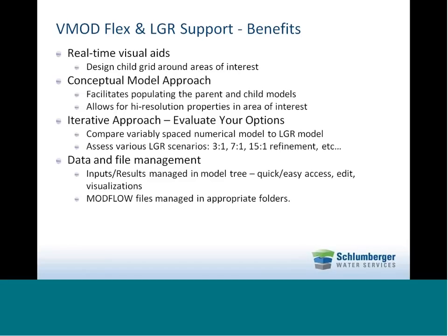The iterative approach in VMod Flex allows you to compare several numerical models, not just a single numerical model. For example, if you're not comfortable with LGR, you can generate a variably spaced grid from your conceptual model, populate that model, run the model, and take a look at the results. And then you can generate a scenario with local grid refinement, generate a numerical model for that, and also within it, with a few clicks, generate the inputs, translate and run it, and take a look at the heads. So it's pretty much unlimited how many numerical models you want to create from a single conceptual model.